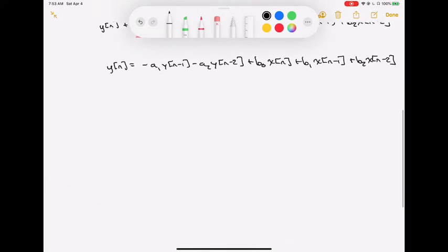So what am I going to do? I'm just going to start by drawing an output path that is going to be this signal that I desire, the output of the system, y of n. That is just me writing out here this left side of the equation, y of n. What is y of n comprised of? Well, it's comprised of a lot of terms, right? It's got some delays of the output as well as the input and delays of the input, and a bunch of scaling of those terms as well as some sums. So I'm going to need some basic fundamental blocks. I'm going to need a way of delaying a signal. That's just physical memory.